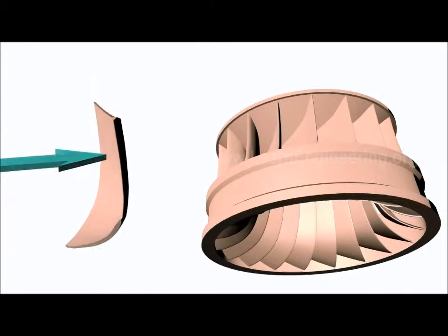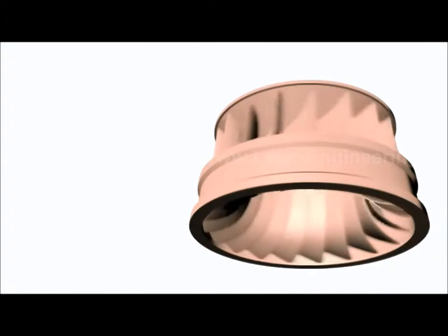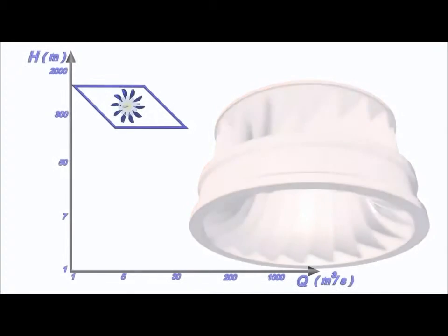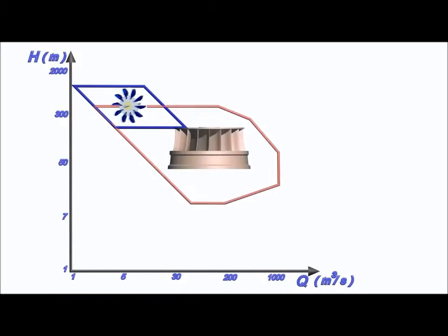Francis turbine is not a pure reaction turbine. A portion of force comes from impulse action also. This graph gives a clear idea about when to use which turbine, depending upon available water head and flow rate.